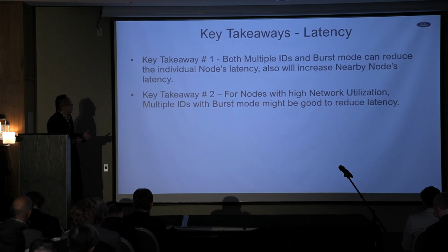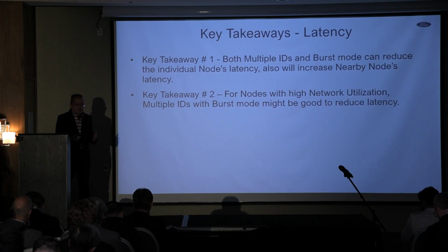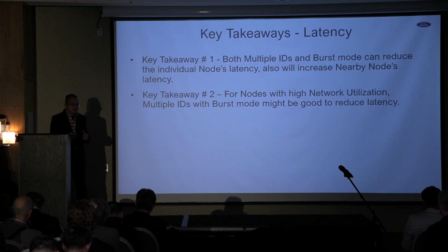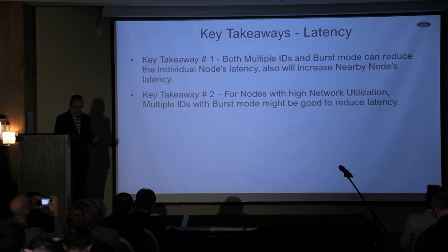So going back to how to configure the PLCA for the latency, the burst mode and the multiple IDs can also reduce the latency. But when we configure the PLCA, we also need to think about the nearby node. We need to think about the whole network, not just the individual node and its bus utilization. We also need to think about the nearby nodes, which is the important thing when configuring the PLCA for network latency.